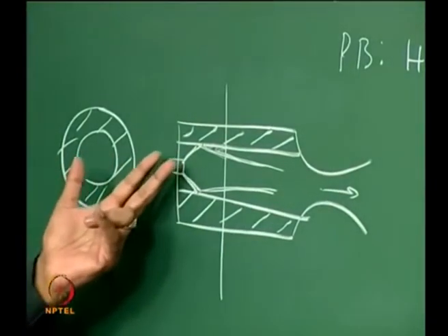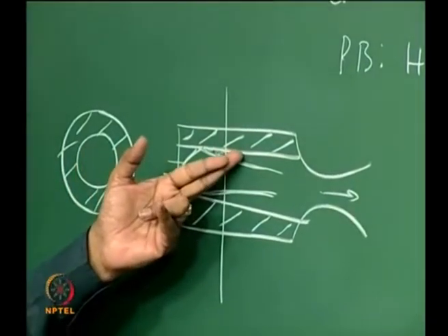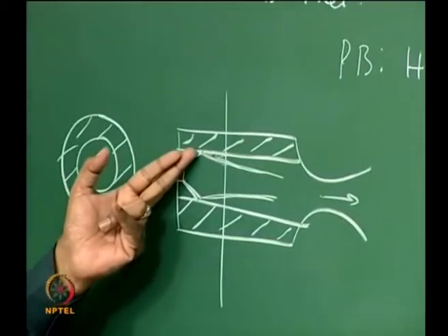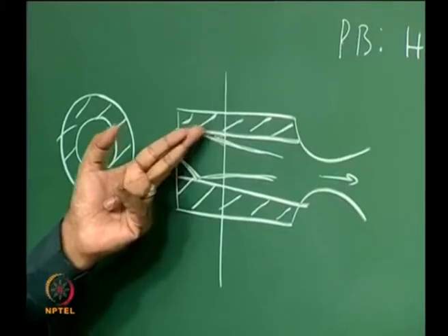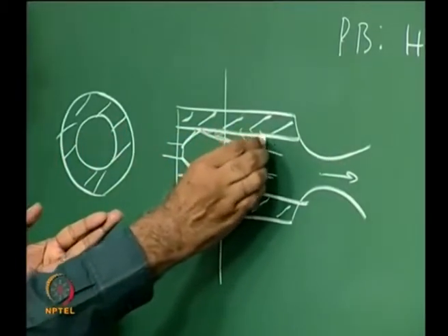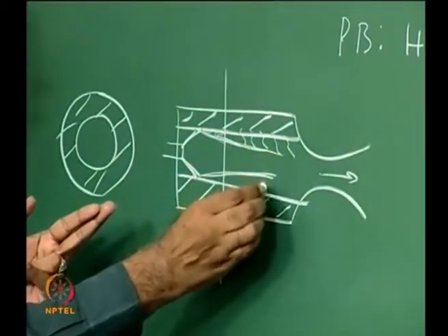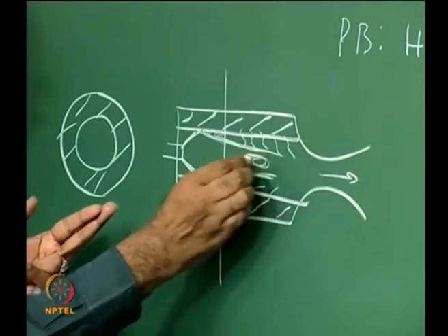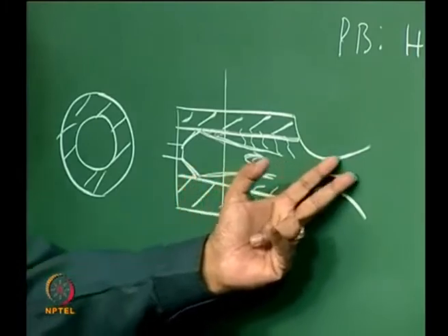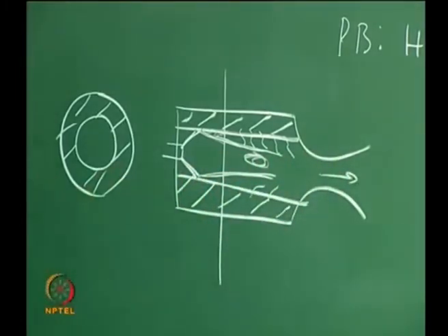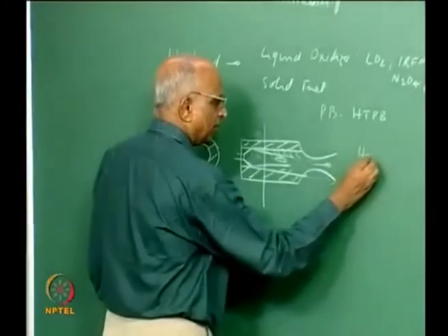Provided the surface is hypergolic, the moment you inject the oxidizer, chemical reactions begin to occur. The heat feedback to the surface generates the fuel vapor, say hydrocarbon vapor, and that hydrocarbon vapor mixes with the oxidizer and you get combustion, which is exhausted through the nozzle. This is the principle of hybrid rockets.